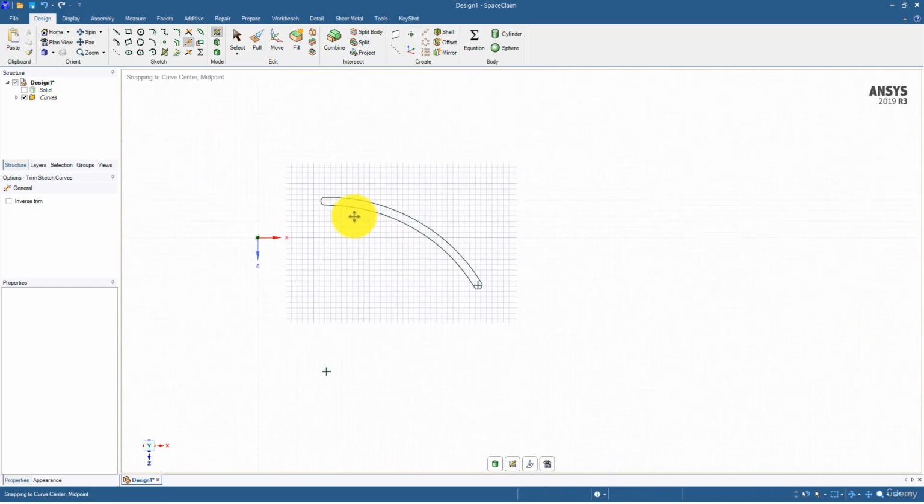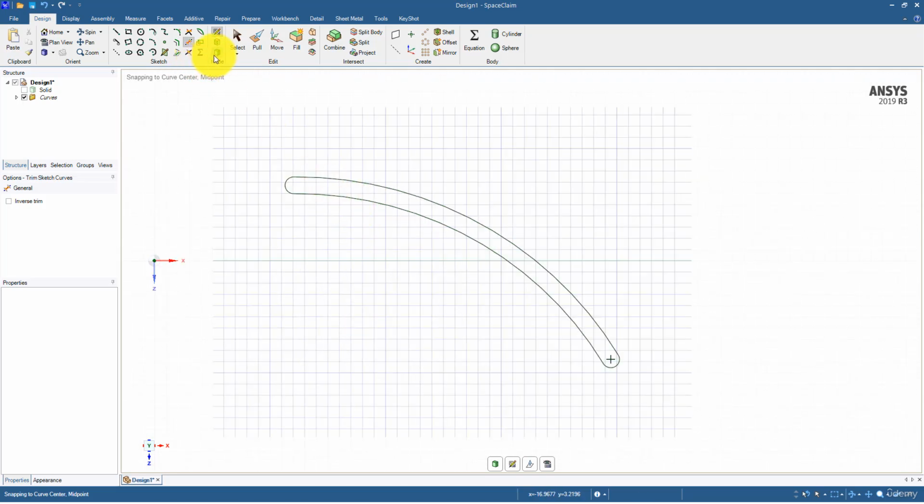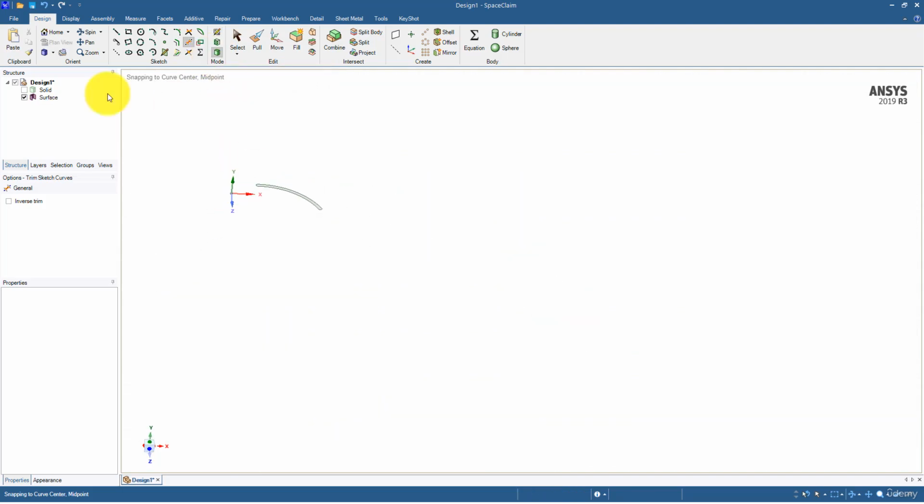So this is some sort of the aerofoil, and if you have some particular design for the aerofoil like NACA 0012, you can implement this over here as well. Okay, now go back to 3D mode and display also the solid body, which is the hub for this swirler.